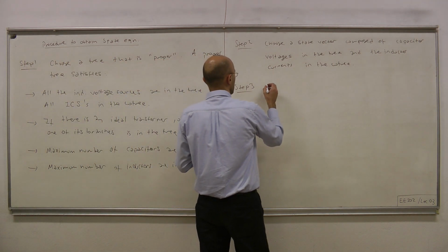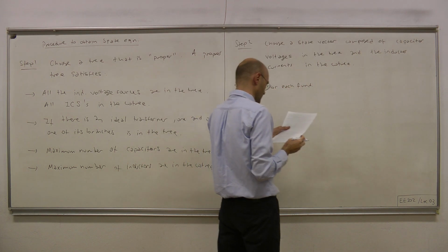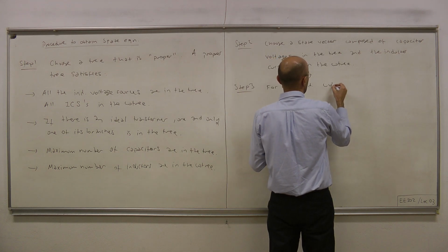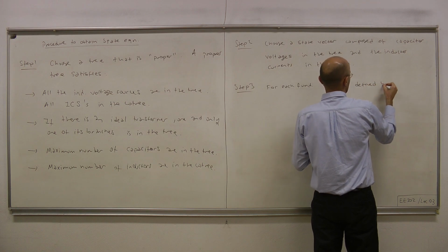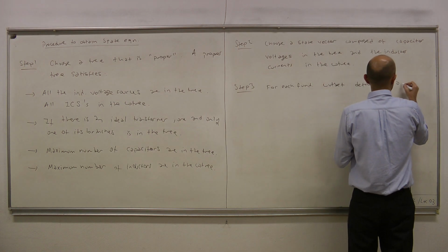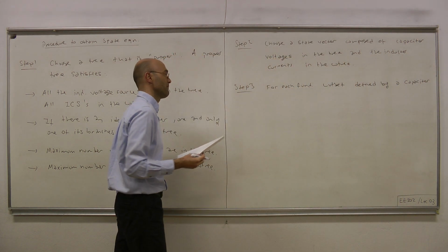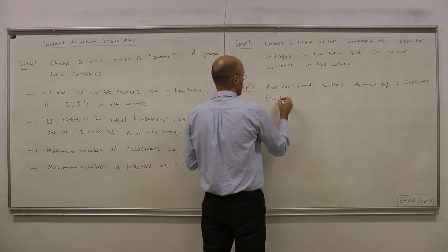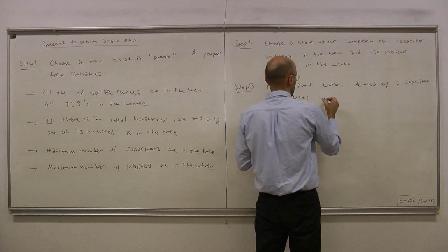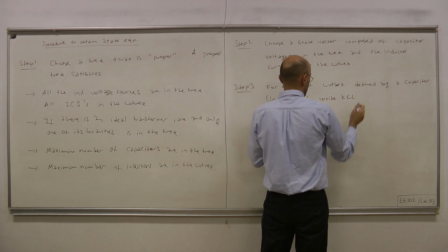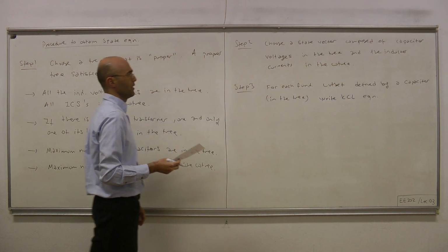So for each fundamental cutset defined by a capacitor in the tree, or in our proper tree, write KCL equation, like the current equation.